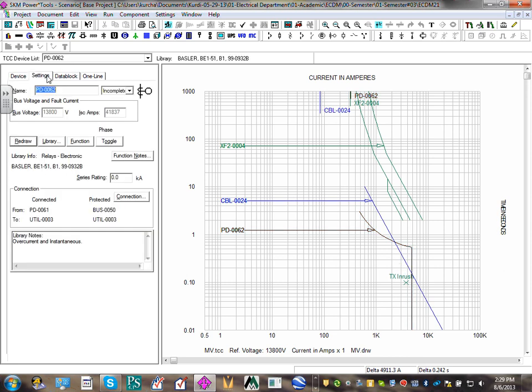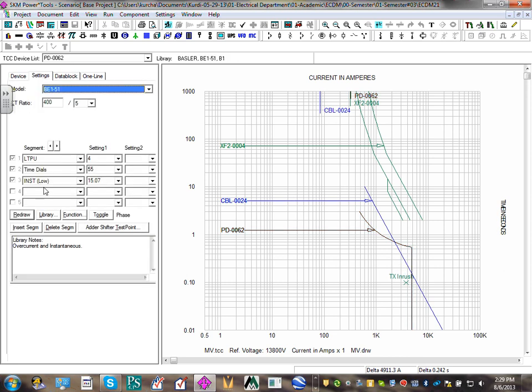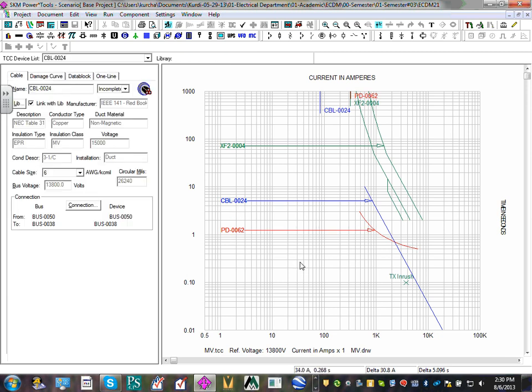And what they do now, if the instantaneous here is on, I'm going to delete the instantaneous and see what's going to happen to this cable. Delete the segment. Can you guys see what the relay is? By the time the relay picks up here, your conductor right here underneath it, that blue thing, will be completely burned, because I don't have an instantaneous whatsoever. So anyway, just to give you an idea, that's coordinating with relays. You might have to upgrade your conductor in the medium voltage.